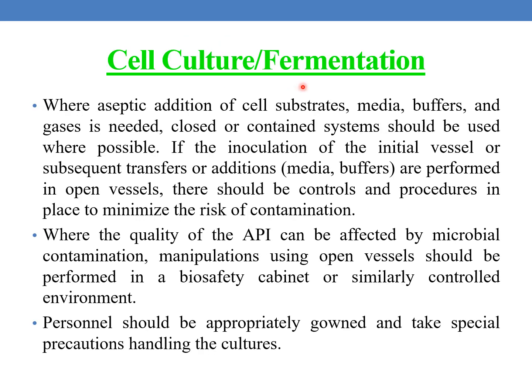Coming to cell culture and fermentation, where aseptic addition of cell substrate, media, buffers and gases is needed. Closed or contained systems should be used where possible. If the inoculation of the initial vessel or subsequent transfers or additions, for example media or buffer, are performed in open vessels, there should be controls and procedures in place to minimize the risk of contamination.